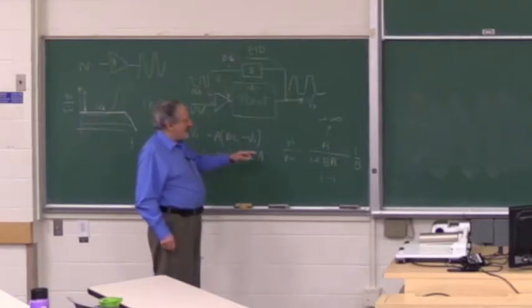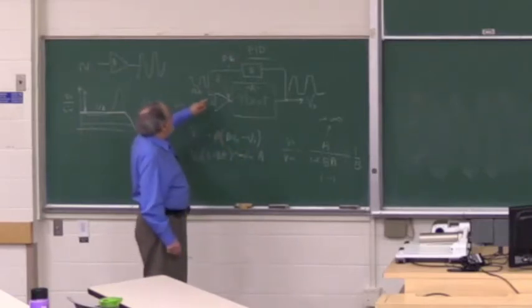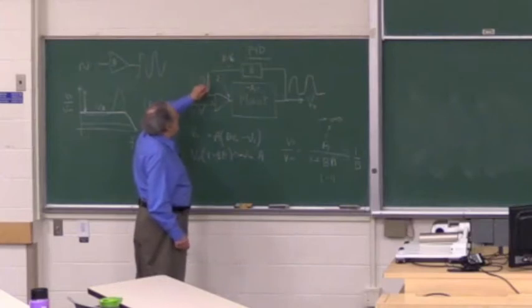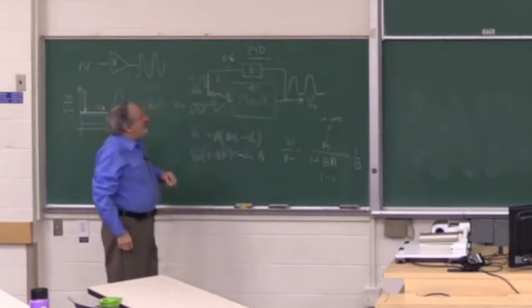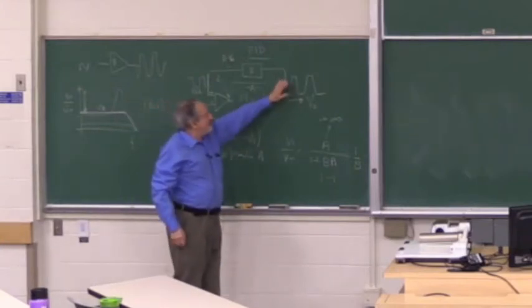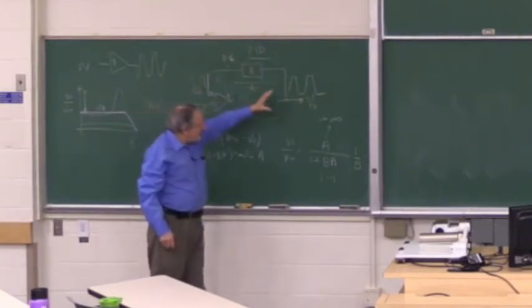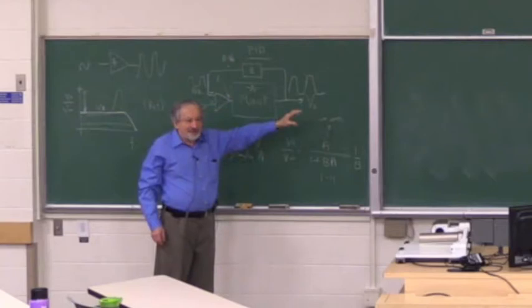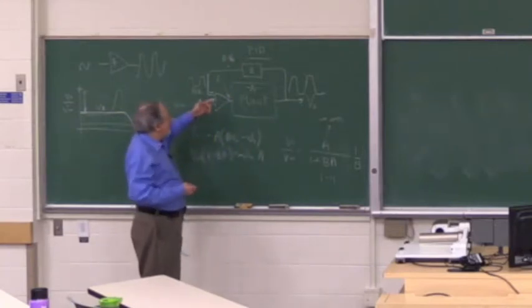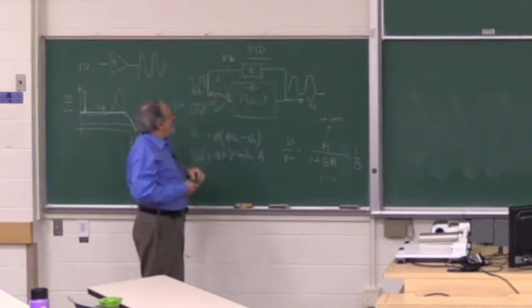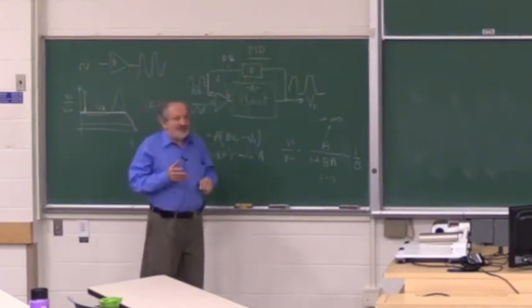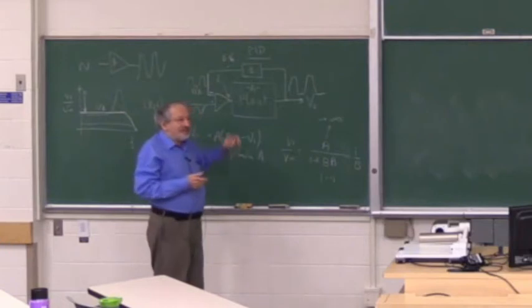This will become unstable because this is connected as negative feedback. The feedback is connected to the minus. So if the signal is too big, because it comes in negative, it brings it back to being small. But if you reverse the polarity, it can do the opposite. If the signal becomes too big, it will come in and make it bigger.